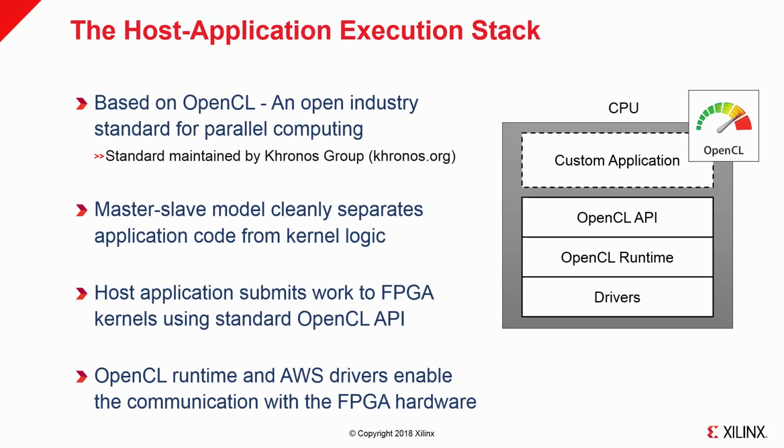After this look at the hardware components, let's now review the host-side execution stack. As mentioned earlier, the stack is based on OpenCL, an industry standard for parallel computing. OpenCL follows a master-slave model which cleanly separates the application code from the kernel logic. Using the OpenCL API, the host application transfers data and submits tasks to the acceleration logic in the FPGA. The OpenCL runtime dynamically schedules and orchestrates the communication between the host and the FPGA.